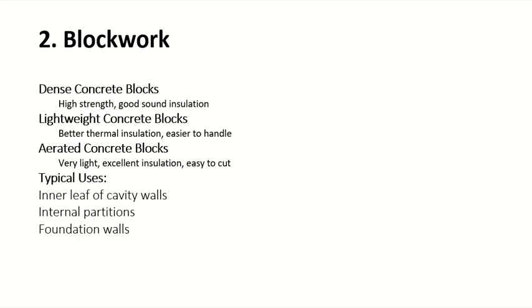Aerated blocks have air induced in them, not because of lack of compaction. If you do not compact the concrete properly, it will have air bubbles inside. That is not aerated. This is your laziness, we don't want to do this. There are some blocks which are specially designed as additive blocks. We do the compaction and then we induce air in them. We put some chemical in them which will later on create air.